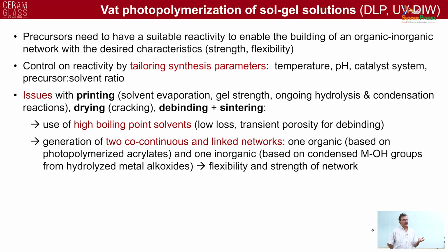You need to control and tailor the synthesis parameters for the sol-gel system: the temperature at which you operate, the pH, the catalyst system, and the precursor to solvent ratio. And you certainly have, as I mentioned, issues with printing. You have solvent evaporation, and for conventional sol-gel processing the solvent is alcohol.